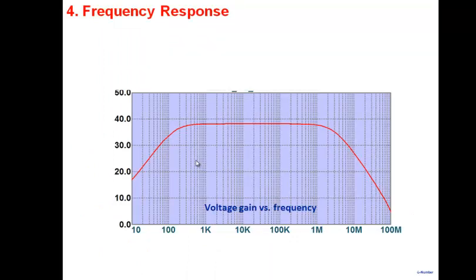So that was a discussion related to harmonic distortion and voltage swing. The next important point is frequency response. All of you have seen this graph, which shows gain versus frequency. There's a region where gain is flat, and then the gain drops at higher frequencies. Gain may drop at lower frequencies or may not. That depends on the kind of circuit that you have here.